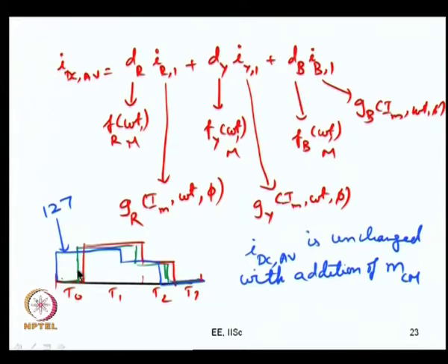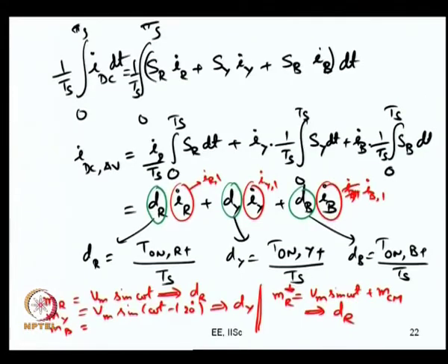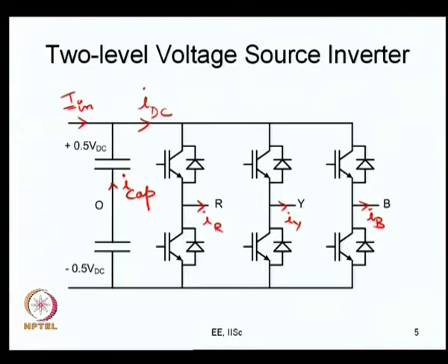So, today what we have tried to do is just get a feel for this problem and how we can relate the DC link currents and the AC side currents. We have primarily got that now, and what actually remains to be done is to come up with this I cap. For this we need to get a clear expression for IDC, and once you have this IDC average, you can get a further average of this IDC over the sector, that is its periodicity, and that will give you the DC current. This DC current flows from the supply, and we can assume the rest of the ripple to be flowing from here now.